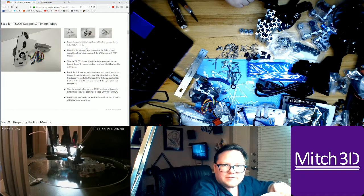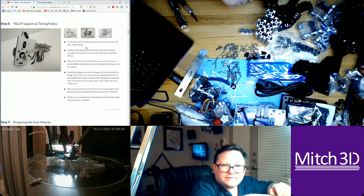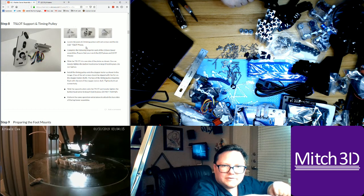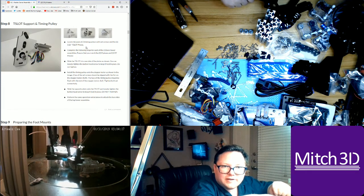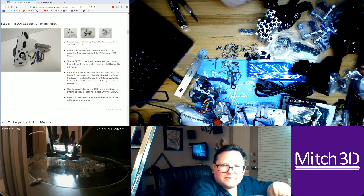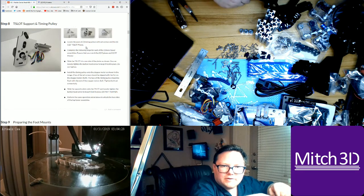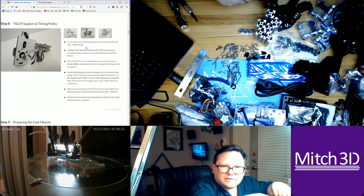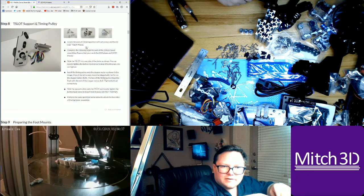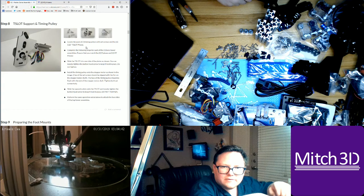Complete the following steps for each of the 3 base tower assemblies. Ensure that you match 2 Z pieces and the 4 XY pieces. Slide the T slot into one side of the plate shown. You can loosely tighten the button screws to keep it in place. Do not overtighten. Install the timing pulley onto the stepper motor as shown. One of the set screws should be aligned with a flat. The face of the timing pulley should be flush with the end of the stepper motor. Tighten both set screws fully. Slide the opposite plate onto the T slot and loosely tighten the button head screw.